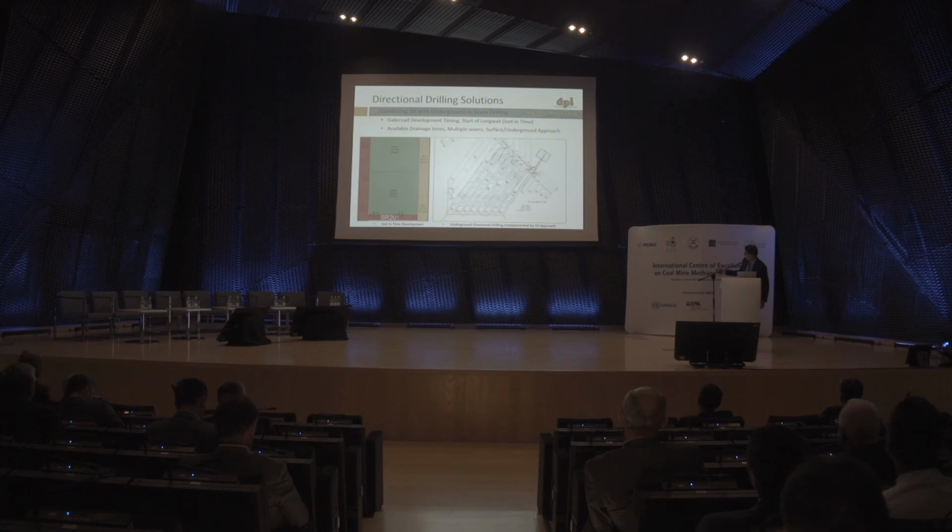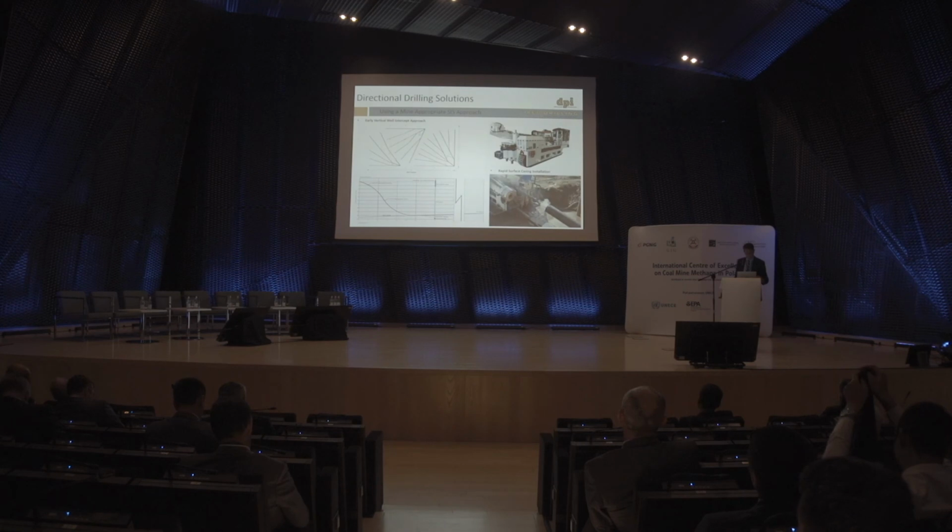So this is a mine in northern Mexico that we've designed a degasification program from. Brand new mine coming in from some slopes, and what we would do is directionally drill from the slopes already and start degassing in advance of mining that seam. And then once we got underground, we would drill from underground as appropriate. But all of these other boreholes that we're showing here, those are all initiated from the surface. So coupling underground techniques with vertical techniques to effectively reduce gas content and allow high performance mining and schedules to be achieved.